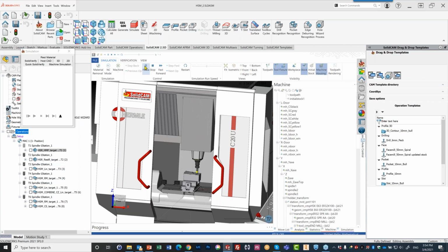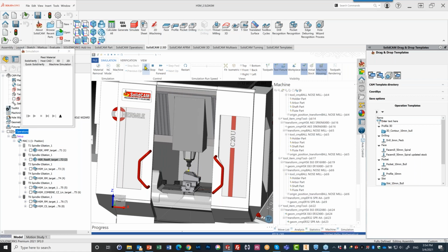And you can see that I can run my simulation here without any issues, even though I'm in the edit-only version, the ShopFloor Editor. Now, what we mentioned before also is we have ShopFloor Simulator. What is the difference between ShopFloor Editor and ShopFloor Simulator? ShopFloor Simulator is the exact same thing as a ShopFloor Editor, except that all you can do over here is just run the simulation and also reprint the G-code.